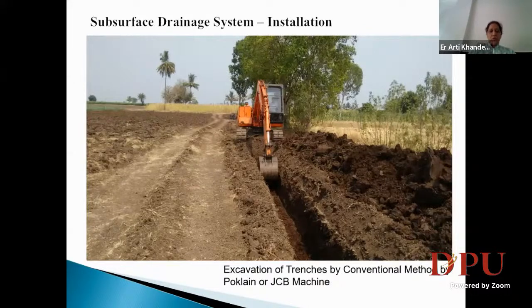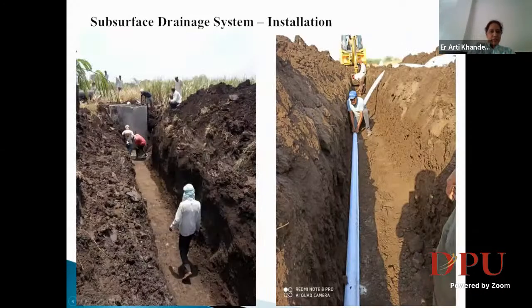We lay down the whole trenches. We can see that after we excavate the whole trenches, we install the pipe like this. We can see that this is a filter above that pipe, and all the water from these sides can come and collect in this collector.